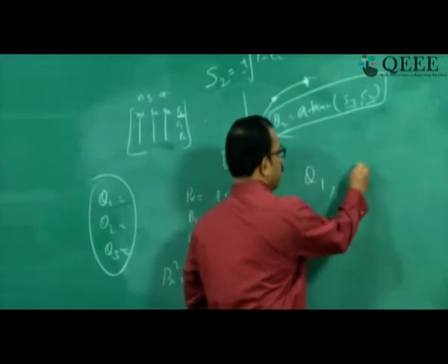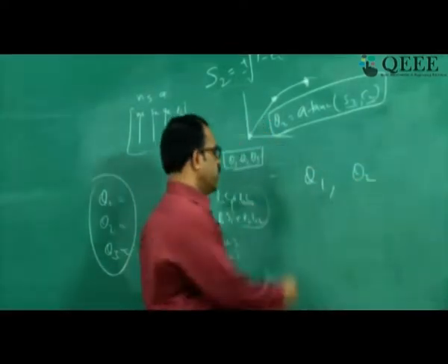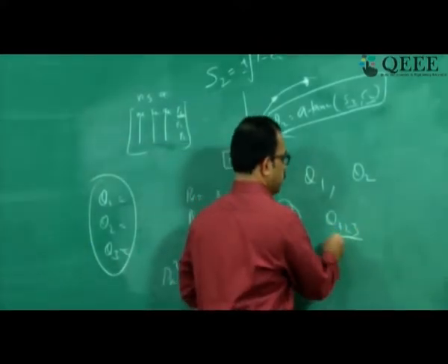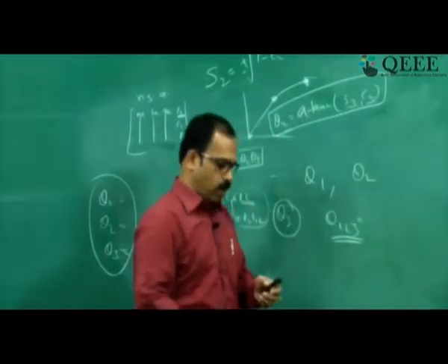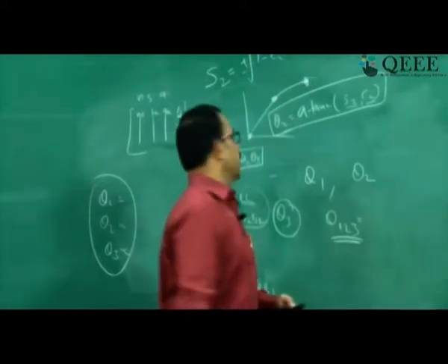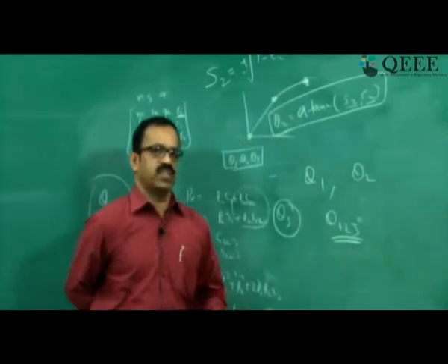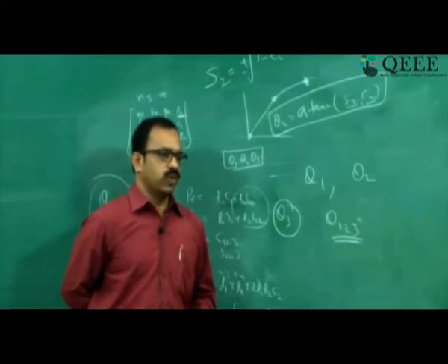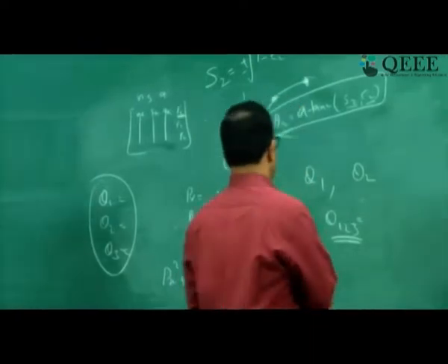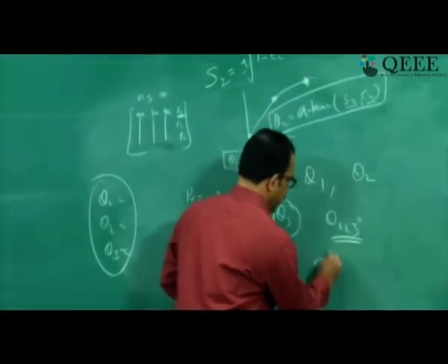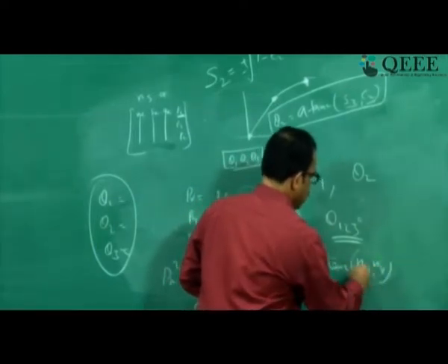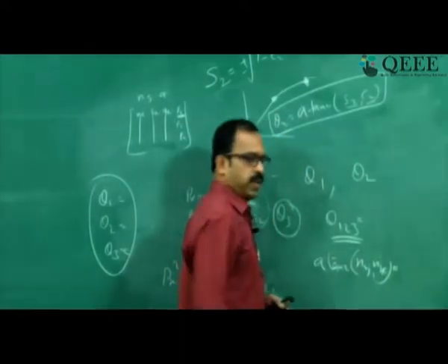So theta 1 is known now and theta 2 is also known, and we need to get theta 3. So to get theta 3, we will find out what is theta 1, 2, 3. Theta 1, 2, 3 can be obtained from equations 1 and 2, that we had, the nx, ny and sx, sy relationship. From 1 and 2 we get theta 1, 2, 3 is atan2(ny, nx), because we know ny and nx. So atan2(ny, nx) will give you theta 1, 2, 3,